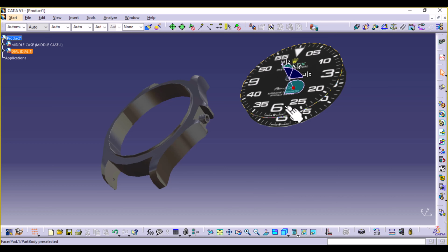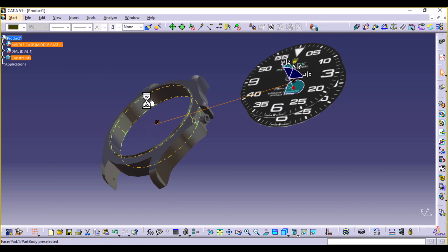And that is the axis of this circle with the axis of this circle. So select coincident constraint. And if you select the side of the circumference, you can see an axis. So select it. And then once again, the side of this, select it. So now we have a coincident constraint, and that's going to make sure they are aligned.